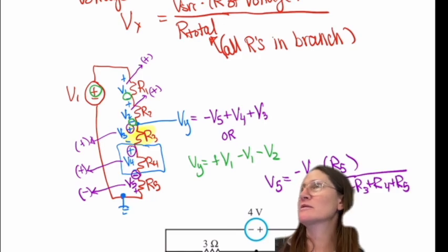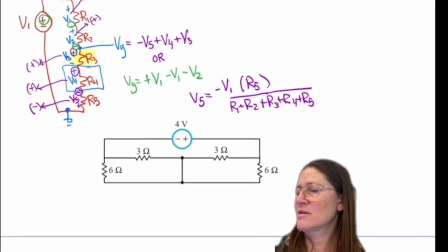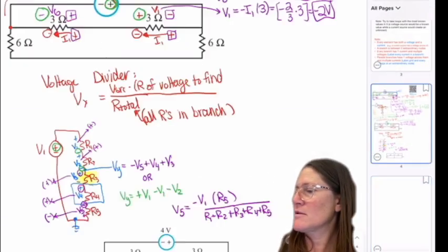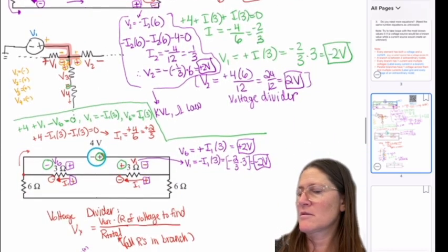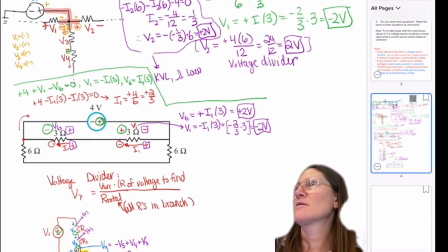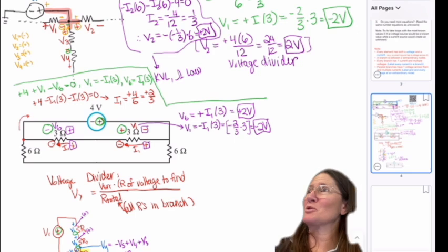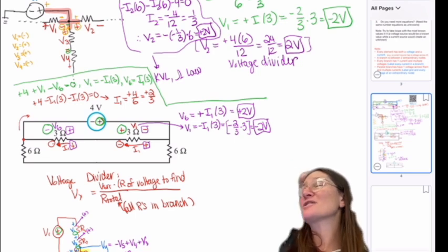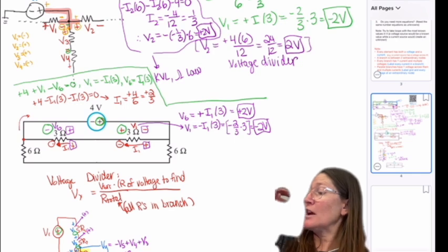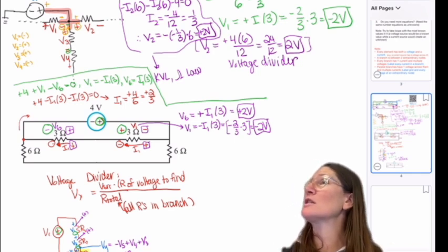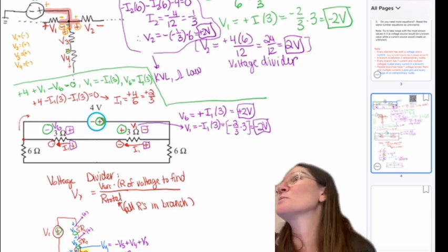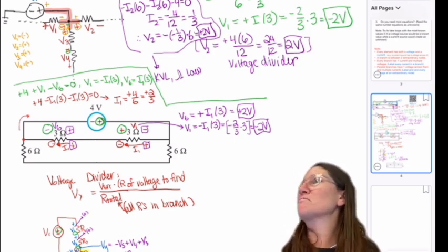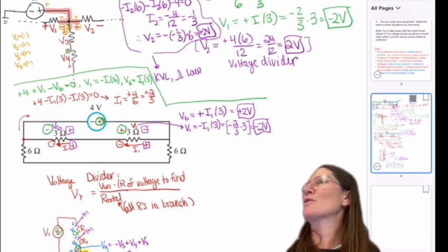Okay, other questions. I guess we assume that positive voltages flow out of the positive side of the voltage source, right, from negative to positive. So if we're given a problem that says negative 4 volts, do we assume that's flowing out the negative side or out the positive? You treat it just the same, so it's still going out of the positive side. If it's labeled, great. If not, you get to pick. And you could be wrong if you arbitrarily put it in there; when you solve it, you'll find a negative value. Again, that just means it's flowing the other way. So just keep them the same, typically flowing out of the positive.